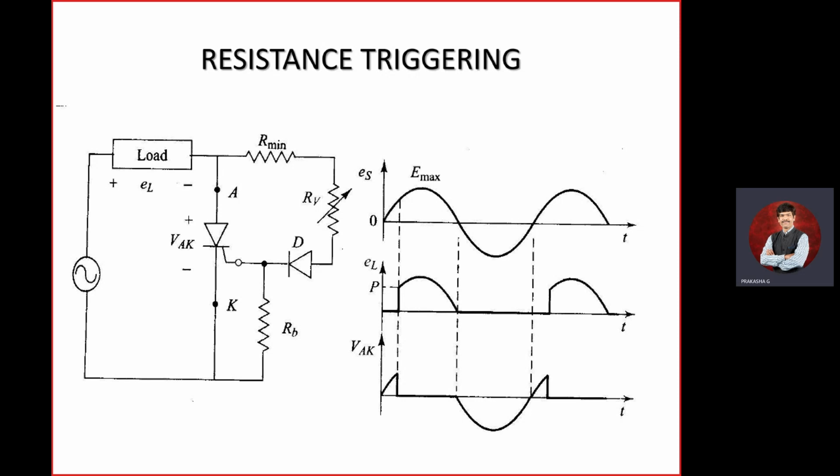Now once it comes here, you can raise a question saying, sir, the input voltage is already low, so why is it not going down directly here? As it happened at the beginning of your thyristor, why is it not happening at the other end, when it is going negative? Because discharging takes place, and at the time of discharging it consumes time. As it keeps discharging, the voltage keeps decreasing. Don't expect it to come down instantly like this. Instantly it will not come. Okay?